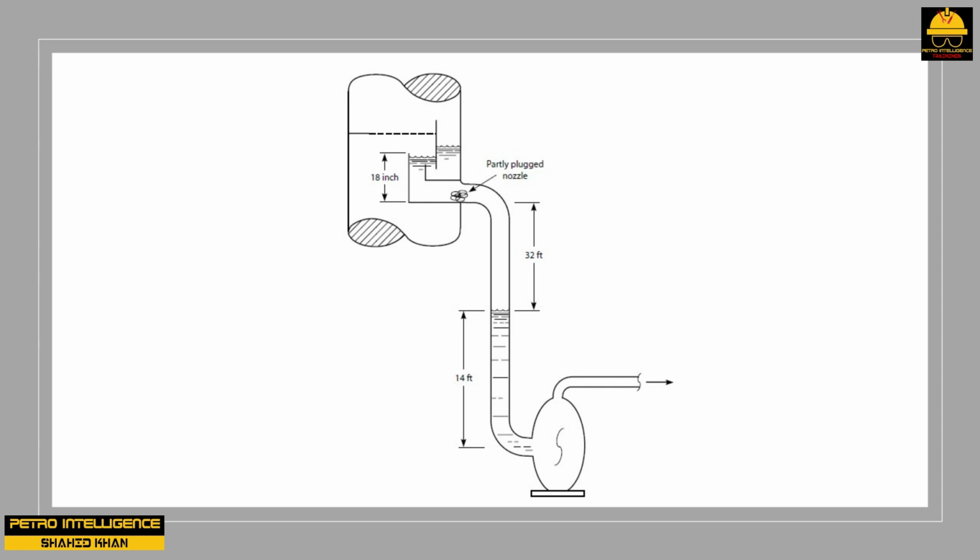We would then slowly lower the water level in the suction line. The water level would creep down, as would the pump's suction pressure. When the water level in the suction line dropped to 14 feet, the pump would cavitate or slip. The flow rate from the pump would drop, and the water level in the suction line to the pump would partially refill. The pump's NPSH requirement would then be temporarily satisfied. Normal pump operation would be restored, but only for a moment.